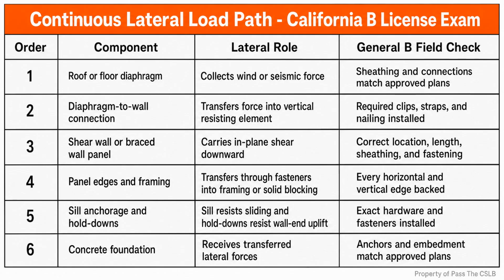That is why my first supervisory question is not, does the wall look solid? My question is, can I trace the load from the diaphragm, through the wall, through the sill and anchorage, and into the foundation without guessing about a connection? That question keeps the contractor in the correct lane. I am not redesigning the structure. I am verifying that the installed work matches the approved plans, schedules, and required hardware.